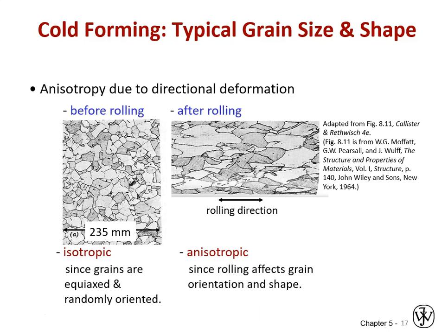And then they piled up and reached the limit of what they could move and activated other directions. And in so doing, the deformation was preferential in the directions of easiest movement. So we actually changed the material by moving those dislocations and ended up orienting the directions of easier movement of the crystal structure in line with the direction of deformation.